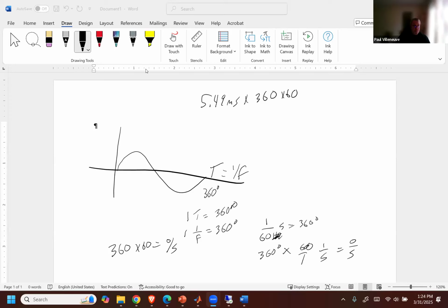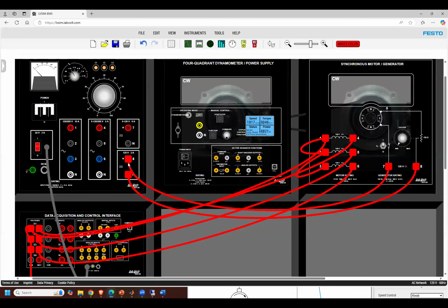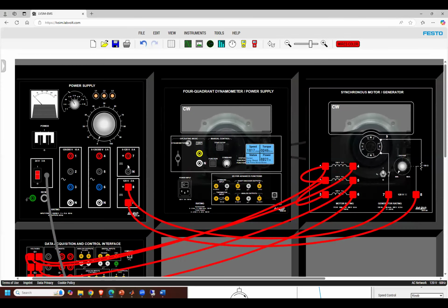But yeah, you can go ahead and check the zero crossings, and you can see I have 120 here. If you did the same thing going from purple to red, you get 120 degrees. So the question on the table is, why is that? Why do I get 120 degrees of physical separation here? That's built into the coil. The windings are physically 120 degrees apart.